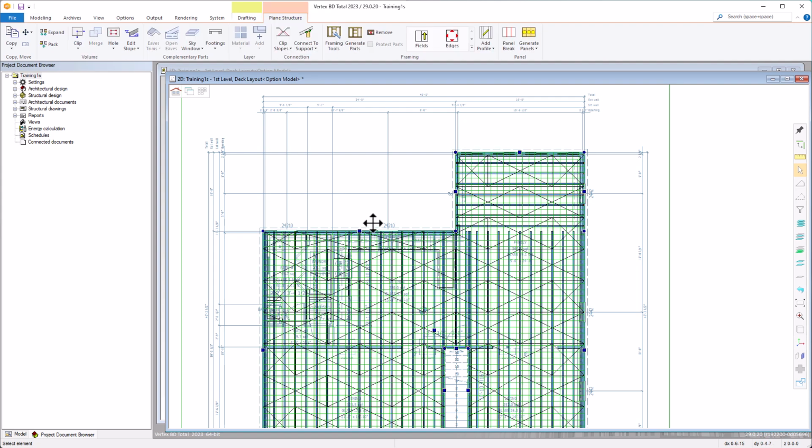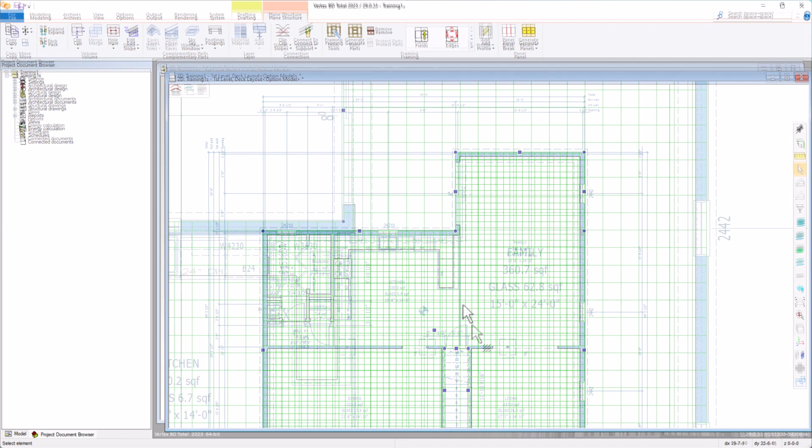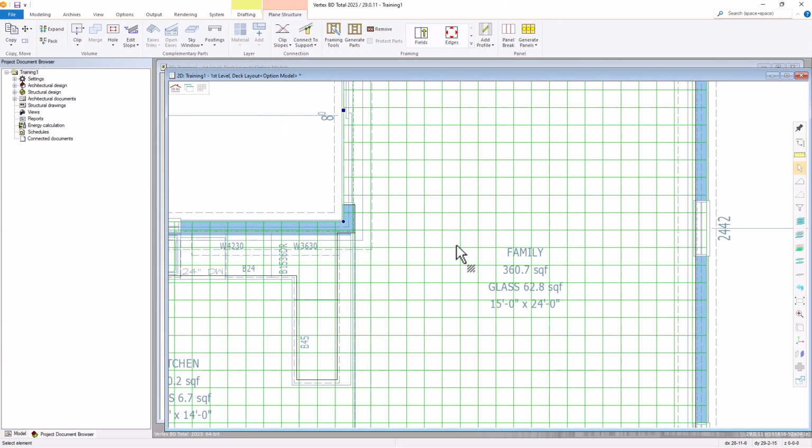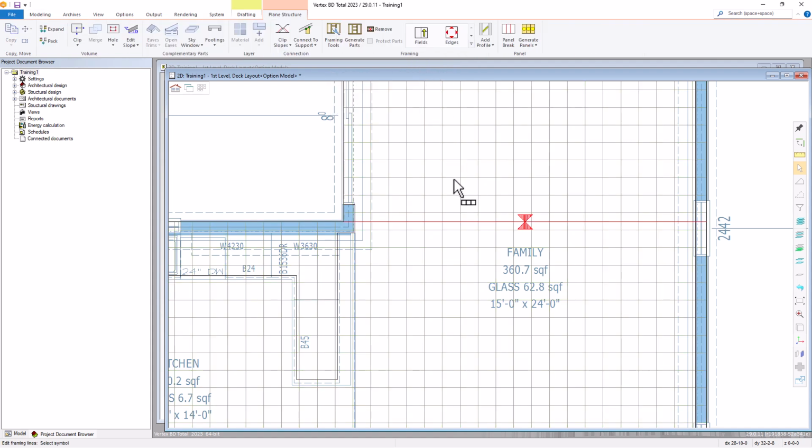With the floor selected, go up to remove, and it removes the framing. We need to add a support member along here to support the joist ends. To add support members and blocking to the floor, we need to work with framing lines. To access the framing lines, with your floor volume selected, go up to Framing, select the More button under the Framing menu, and you'll see Lines for Edit Framing Lines. Click on Lines. Framing lines are shown in red and have an hourglass shaped symbol. In this case, we have a framing line for the split line that we added.